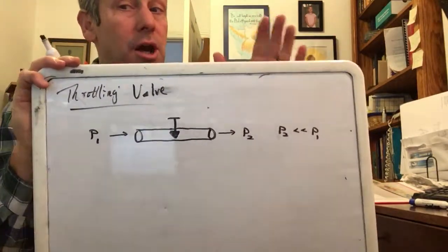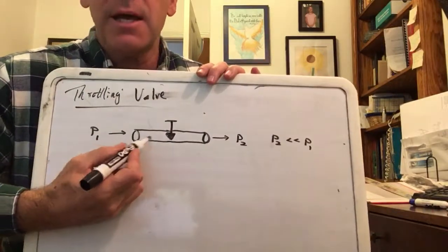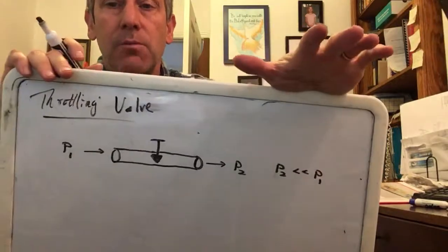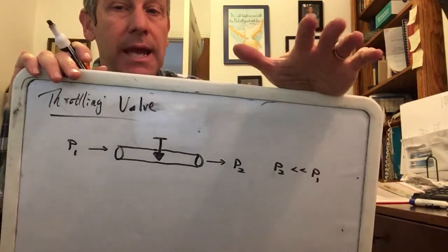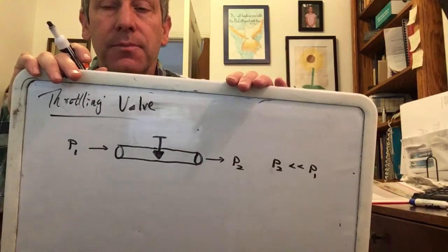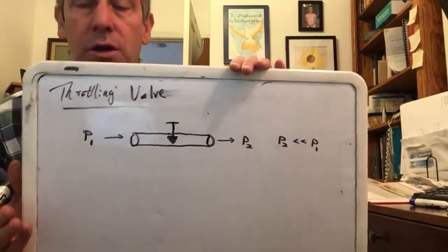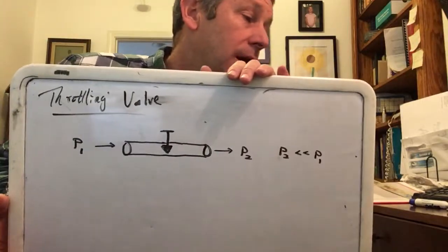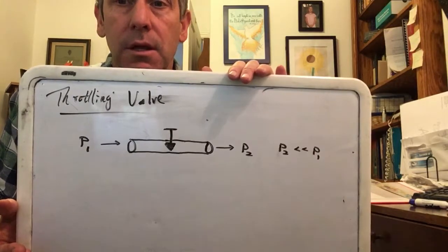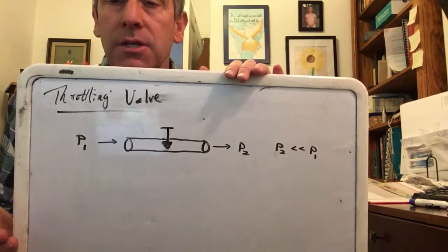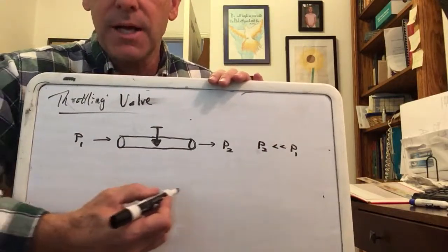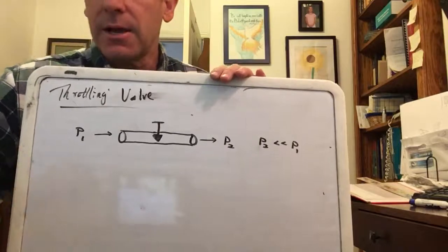Okay, could it operate at steady state? Could m dot in and m dot out be the same? Absolutely. That will be the case because we can't have more mass flow rate into something than out over a period of time. All right, so in short, that would be what's going on with throttling valves. What we want to do in addition is be able to come up with analysis using the first law. So I'm gonna just go ahead and take this throttling valve and draw it as a box that represents a section of pipe. Hang on for a second, please.